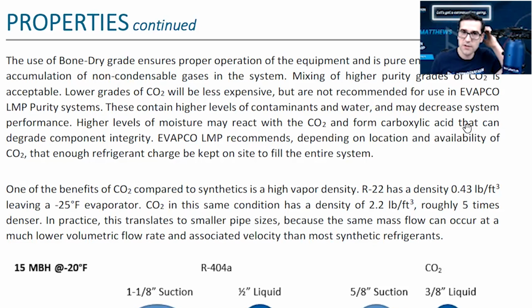And this is like any refrigerants. You can have the POE oil. When you've got POE oil, you've got moisture, you've got heat, it starts to break down that oil, and that's what causes the issue. Once again, you need to go inside your system and look into the sight glass and see if you have moisture in there.